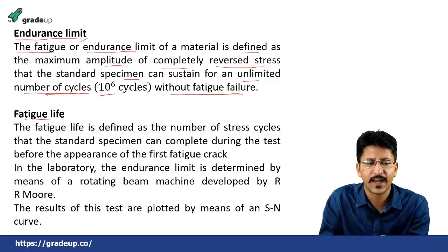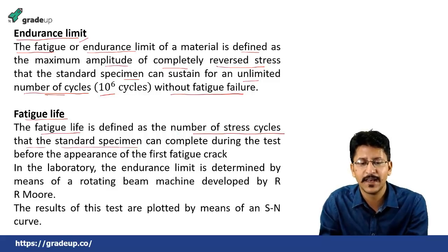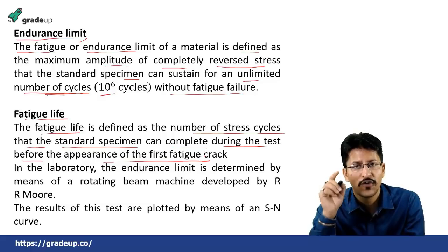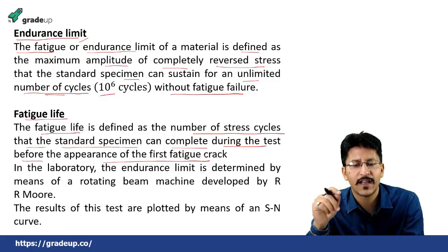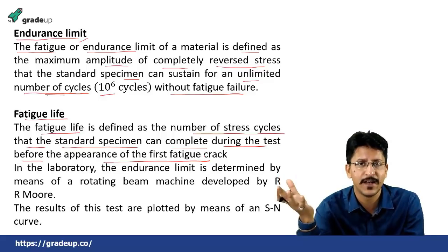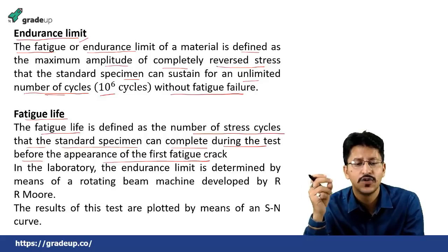Now what is fatigue life? Fatigue life is defined as the number of stress cycles that the standard specimen can complete during the test before the appearance of the first fatigue crack. So before the appearance of the first fatigue crack, the number of stress cycles that a standard specimen or a standard component can withstand is known as fatigue life.